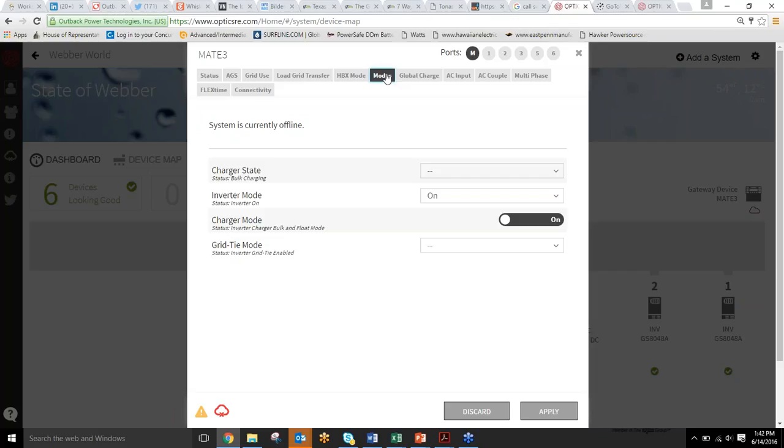Depending on how demand charges are calculated, very typically it's strictly based on the number of amps pulled from the grid at any one point in time, and you either pay for that highest delivery in one lump sum at the end of the month, or depending on where your previous 12 months' history had their highest demand, it may affect your overall billing. What support mode can do is make sure that you stay below a certain amperage limit on what you're drawing from the grid, and support everything else with the inverter system.